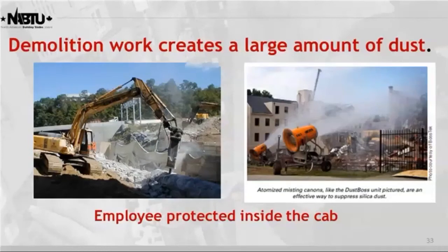But some of the older models may not be so good. You can eliminate a lot of the dust again by incorporating one of the easiest things to do: water systems. So you might see some of these misting cannons or water cannons, or occasionally I've seen where they tapped into a local fire hydrant and used fire hoses to spray the area down as they demoed the building.